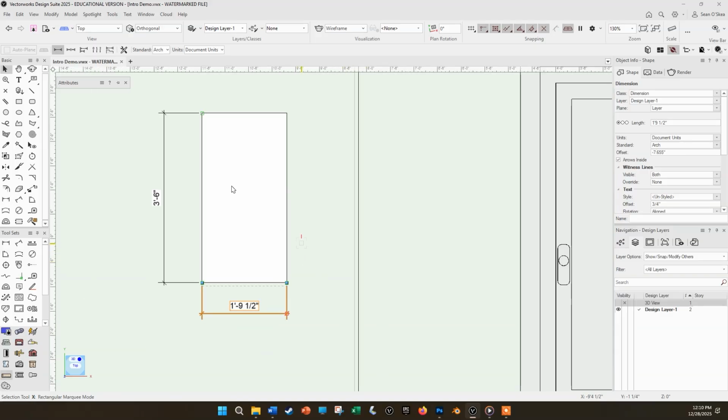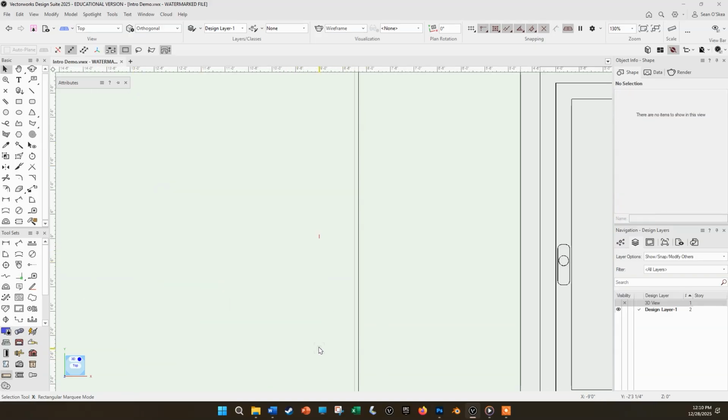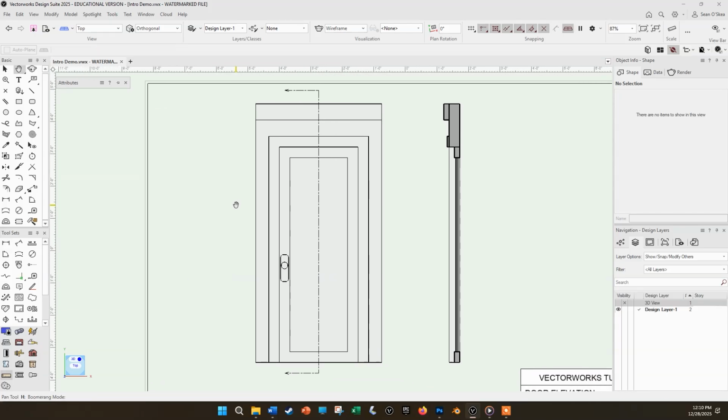Now, I'm going to delete my example and head back to our door flat. And we know the height of the flat is 8 foot 0 inches, so that'll be a good one to start with, to make sure we're doing it right. So remember, all of the snapping is possible because these 6 snapping settings are on, especially this third one, snap to object, that's the one that's doing most of the work.